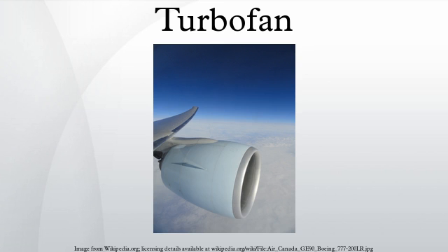Depending on specific thrust, ducted fans operate best from about 400 to 2,000 km/h, which is why turbofans are the most common type of engine for aviation used today, in Euro and airliners as well as in subsonic and supersonic military fighter and trainer aircraft. It should be noted, however, that turbofans use extensive ducting to force incoming air to subsonic velocities.